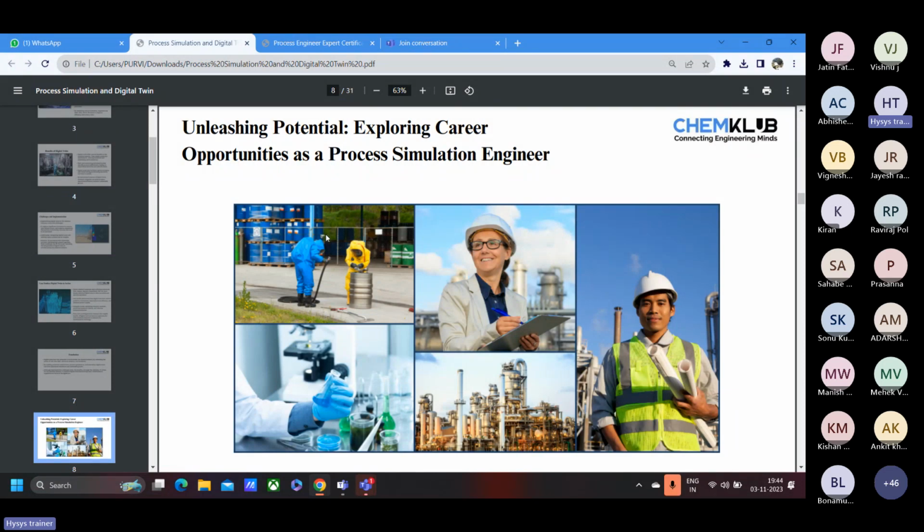So there was a case study on these gasifiers, on how they can reduce the downtime so as to maximize gasifier asset utilization, and then they can produce the syngas, which is from the water gas shift reaction. Then they did a real-time analysis of that model, and they found out that when they mix a certain kind of slurry, like a pet coke slurry, if that slurry percentage is on the higher side or lower side, then they face issues with the filters just after the gasifier.